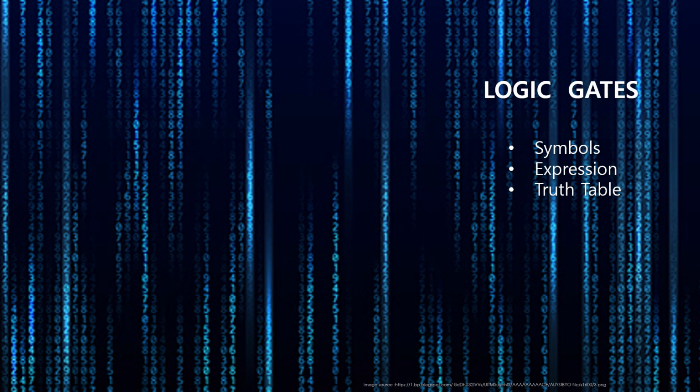And most logic gates normally have two inputs and one output. Of course it can have multiple, but we'll see that later on. So normally any gate has two inputs and one output, and at any given moment every terminal is in one of the two binary conditions that we know, right? Low or high. Low means a 0 and high means a 1, represented by different voltage levels. So we know that 0, the low level, means 0 volt, and if it's high, that is the 1 condition, it means 5 volt.